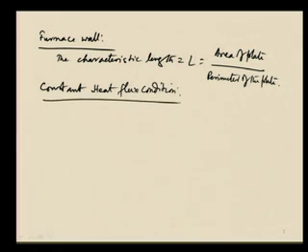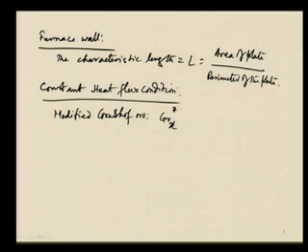What we have seen previously is the isothermal condition, that means the temperature is constant. Now, the heat flux at the wall is constant, and under that situation a modified Grashof number is used. It is sometimes written as Gr_x star, the modified Grashof number, where x means local, a function of x.